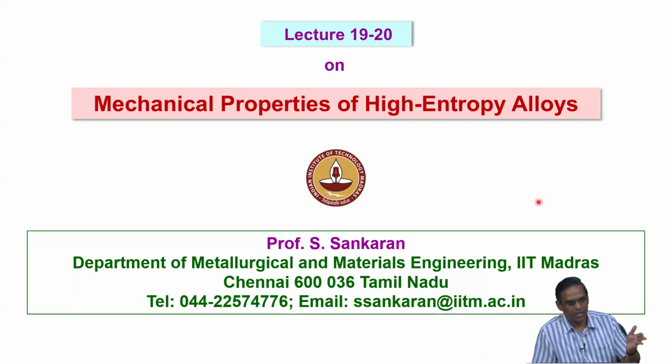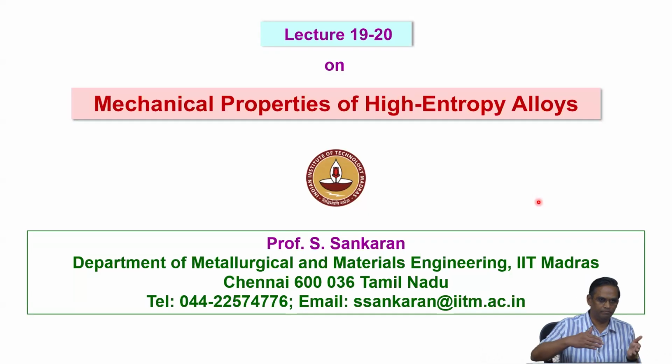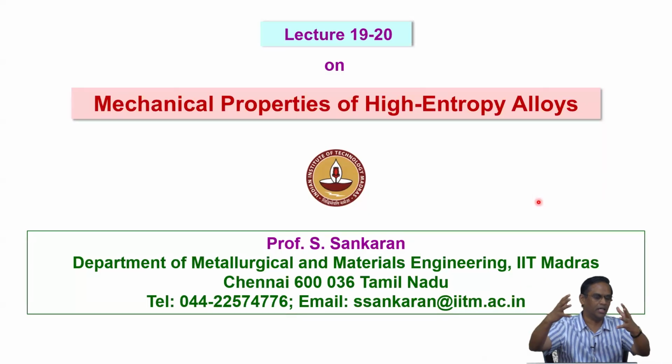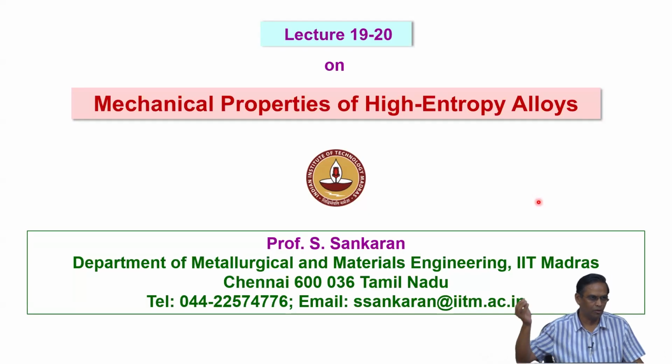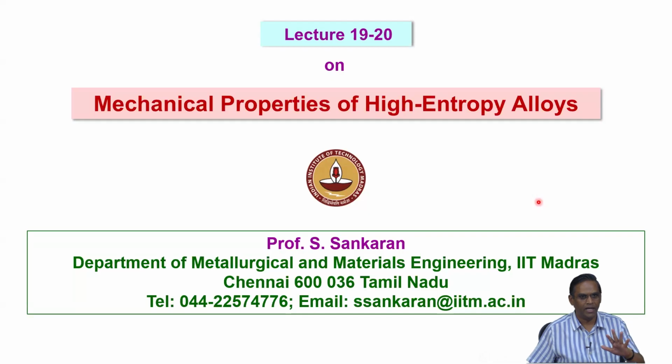So when you talk about a dislocation core, you have two kinds of stress fields. If you consider a classical edge dislocation, the upper side is experiencing compression, and the lower side is tension. So all the substitutional elements can go and occupy the tension region, so that it will reduce that stress, it tries to relax that stress. And similarly, any small atoms can go and occupy the compression stress field, so that will try to relax that. So this kind of idea we should know.